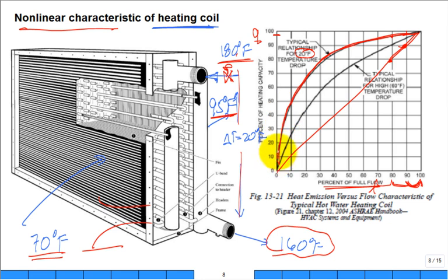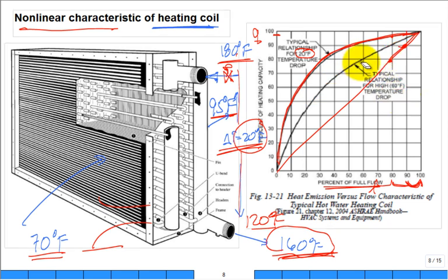Now, why does the UTSA plant really focus on 20-degree? Because they don't want it so cold when it goes back to the boiler. It's easier just to recirculate a lot of water, let it be a 20-degree difference. Somebody says, why don't you have a 60-degree? Okay, well, if you do 60, then it's coming back at 120, and it's going to be a little more mixing of cold water coming into your boiler, and the boiler designers don't like that. It's something about thermal stresses. All right, but it would be less nonlinear if you had a larger delta T. But let's just focus on that 20-degree.